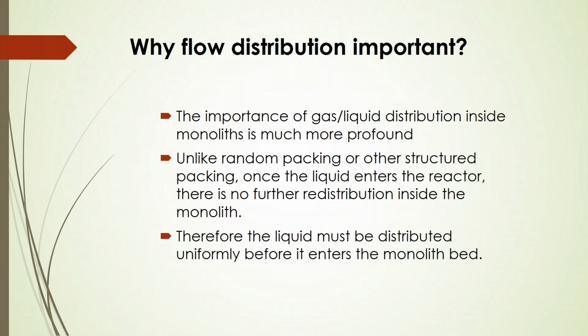So, the importance of gas and liquid distribution inside the monolith is much more profound, and it has to be analyzed. And unlike random packing or other structured packing, once the liquid enters the reactor, there is no further redistribution inside the monolith reactor. Therefore, the liquid must be distributed uniformly before it enters the monolithic bed.